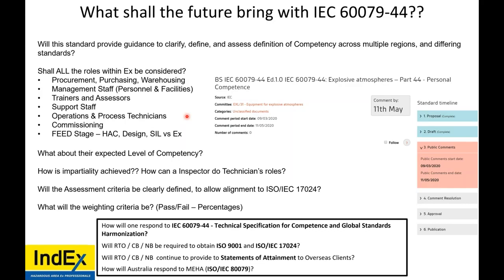Then when we think of safety integrity level, when we talk about instruments such as safety instrumented systems or fire and gas, we're talking about plant integrity and personnel integrity systems. These systems need to be able to operate without failure out of millions of times of operation. Now, it may detect gas, that gas detector, but if it's outside of a hazardous area, doesn't that gas detector need to be rated EX if it's meant to operate in an uncontrolled release of gas?